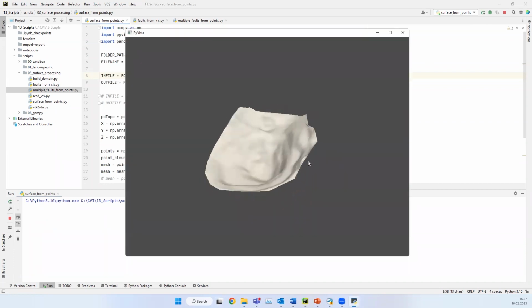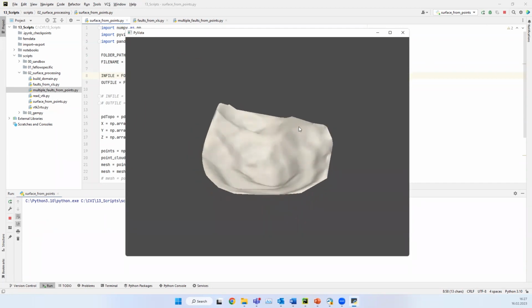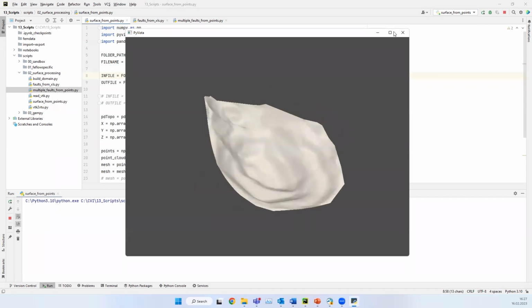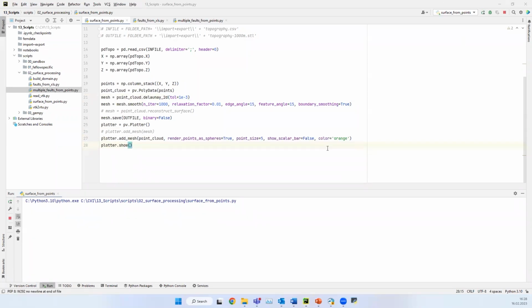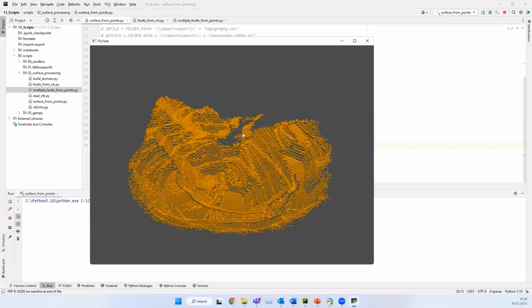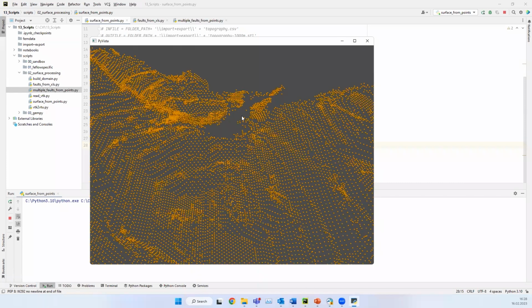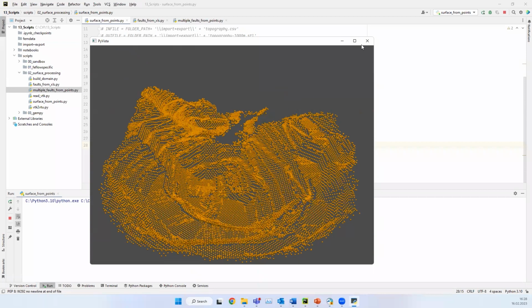Here this is a surface of an open pit, a specific mining level, so it creates a surface. Let me check this and then plot the points. And that's the start. So there's a cloud of points, and then we are using this cloud of points to triangulate. That's the cheapest and simplest way to create surfaces if you don't have a geological model.